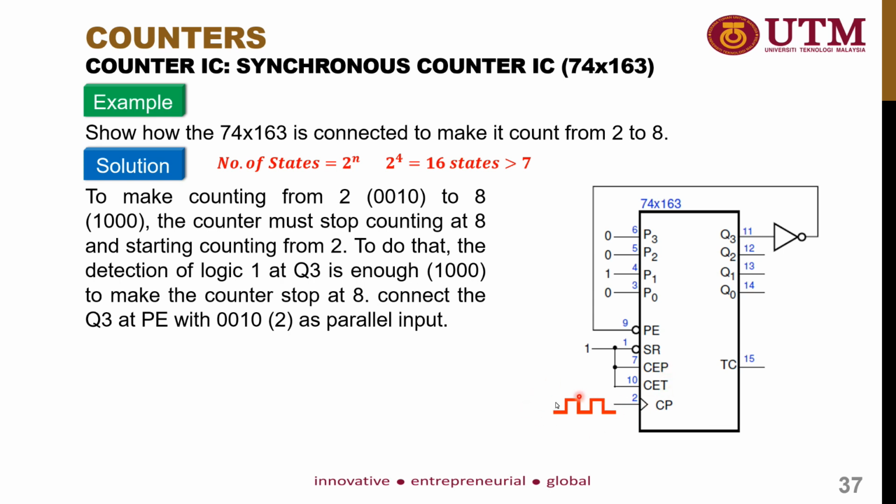So as usual, you need to connect your external input clock. This time, the counter should reset after it counts the number of 8. In order for us to reset the counting to a customized starting value, you need to connect the output that indicates finished counting. This time the counter will finish counting when the output is 1000. So after this state, the counter will be reset.